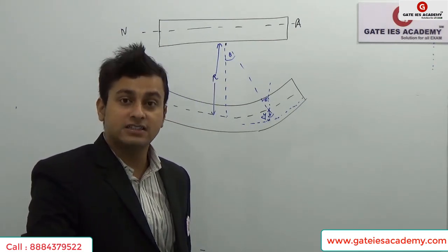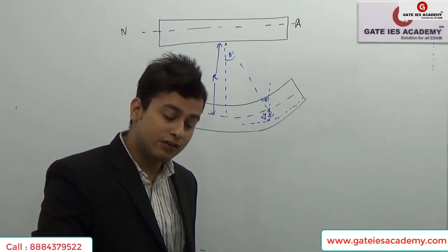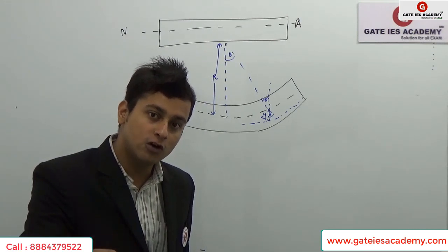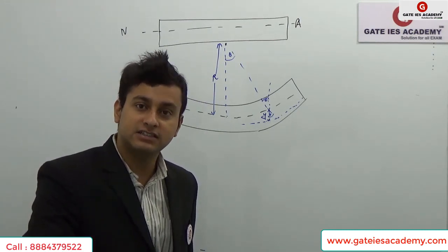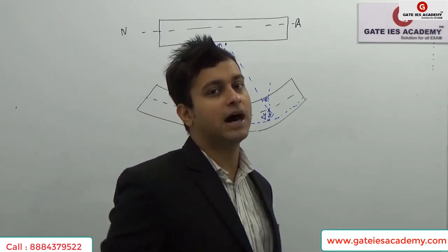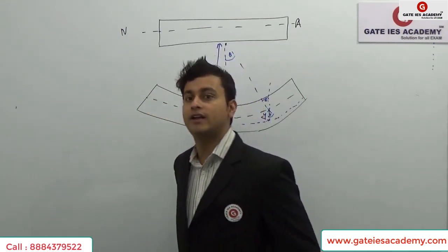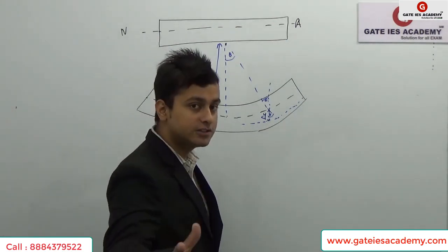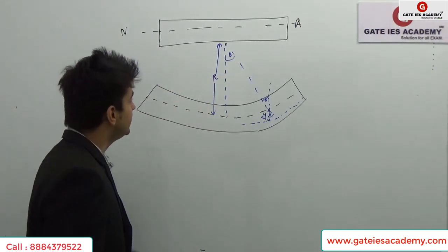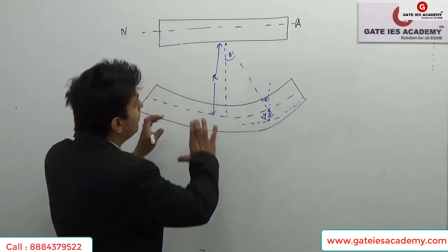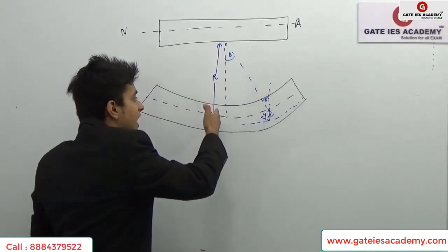Next, Hooke's law has to be followed, that is, we take stress proportional to strain. But for deriving the first part, that is not even required. How? You will see. Firstly, I have taken this beam, and now it is being acted upon by a load, so it bends in an arc of a circle of radius R.